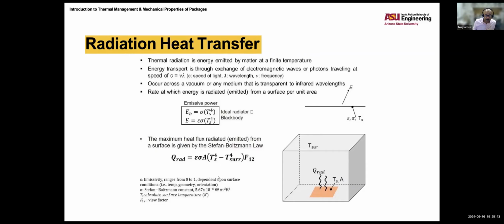So we will add the resistances in series in a linear manner. For those in parallel, we will add them in a reciprocal manner. So the reciprocal of the total parallel resistance is equal to the sum of 1 over each resistor.